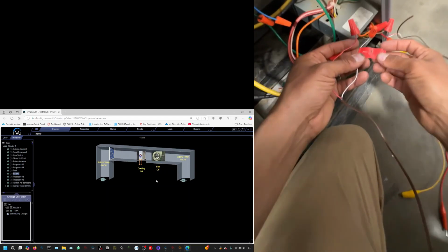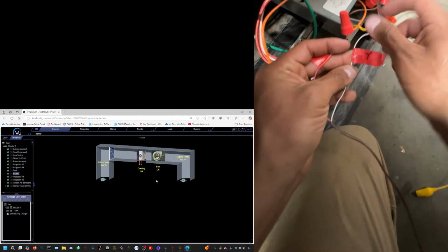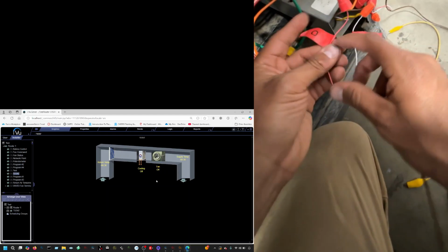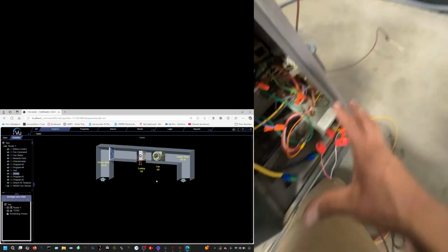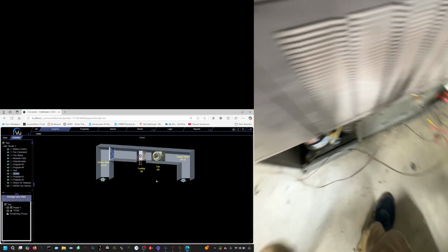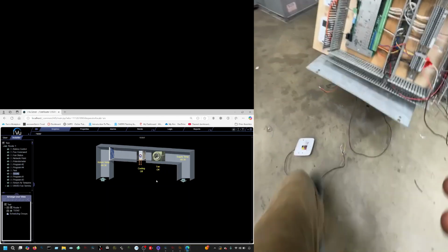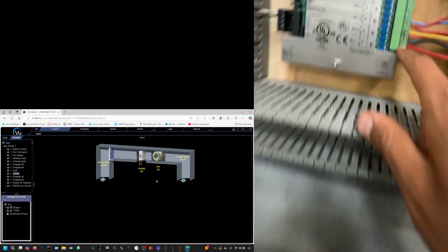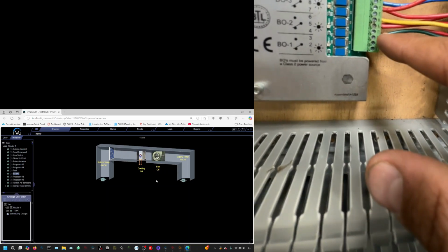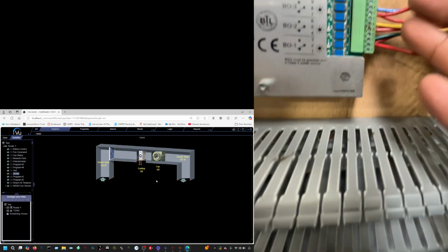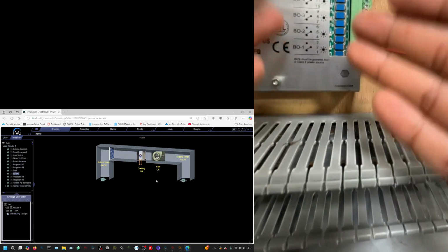So Y goes to my yellow wire, right? And then O goes to my reversing valve. So that's done. So we got that taken care of. So essentially, if I get a little alligator clip from this power and give it to the green one and my yellow one, guess what? We're sending 24 volts to my contactor and my reversing valve.